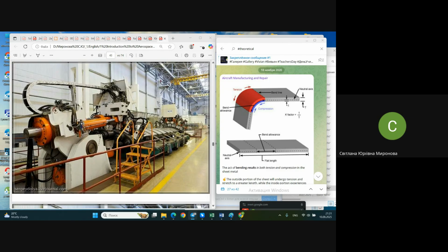But you understand that for big parts, huge sizes, without spring back, and of specific shape where the radii of curvature are very big and curvature is very low, and for these complex shapes, it may be the best choice at all. It's called stretching once again, or stretch forming.